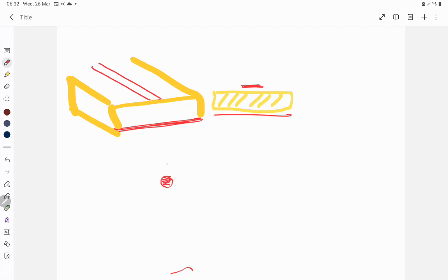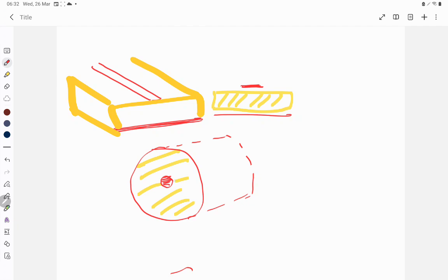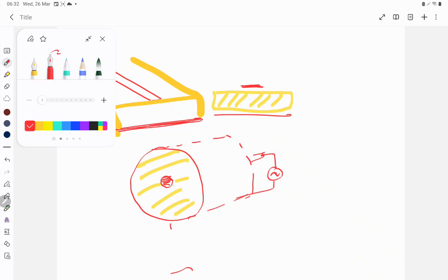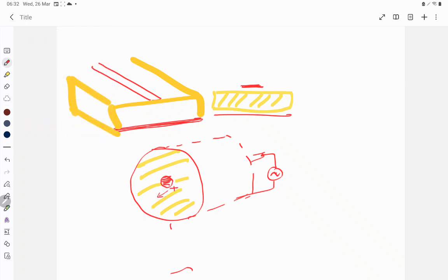So in coaxial line we have a center conductor and an outer conductor, and in between we have some insulator. So obviously if there is a current flowing, and we put some kind of signal, at a point of time and at a particular cross section, we shall have a plus, say positive direction, current flow in the center, and obviously there will be a return path for the current flow, and that is through the shield.